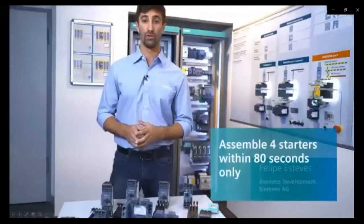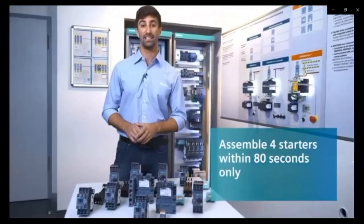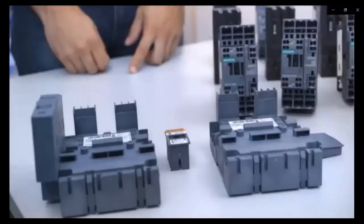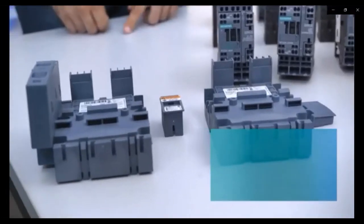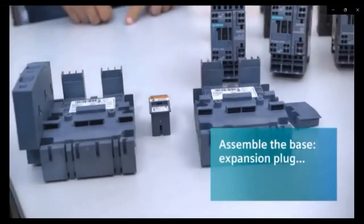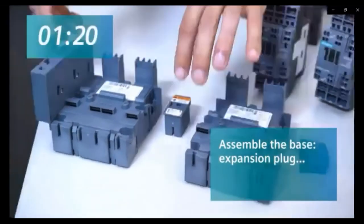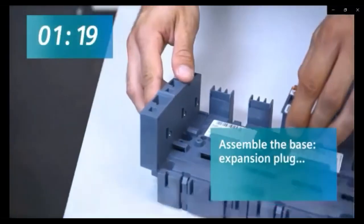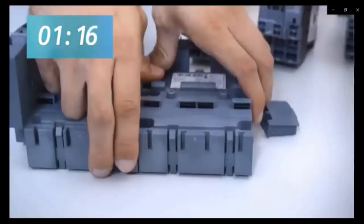Using only my two hands as tools, I will now assemble 4 starters ready for control connection within 80 seconds only. First, I will assemble the base to accept 4 starters using the expansion plug. And to remain finger-proof, don't forget to use the end cover part. Using the proper link module between the contactor and the MSP, I'm now assembling the 4 starters.